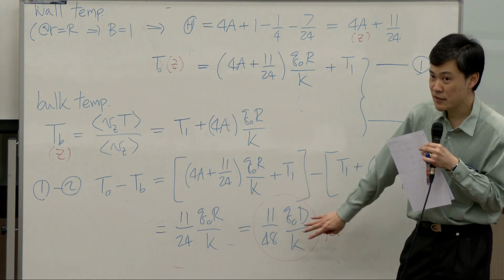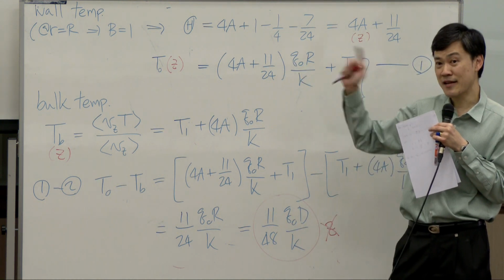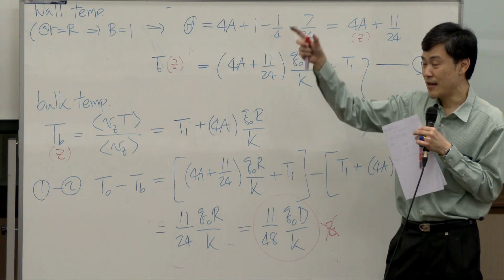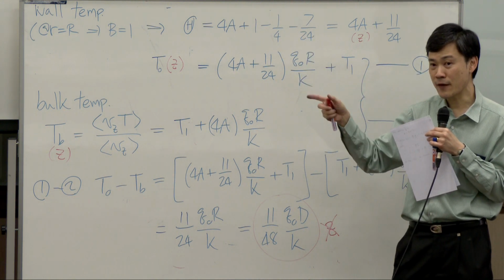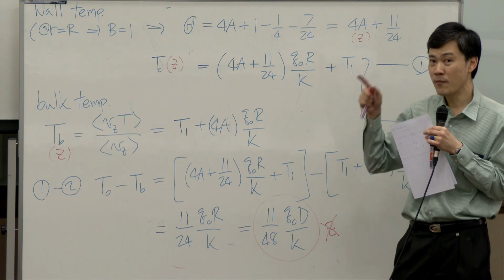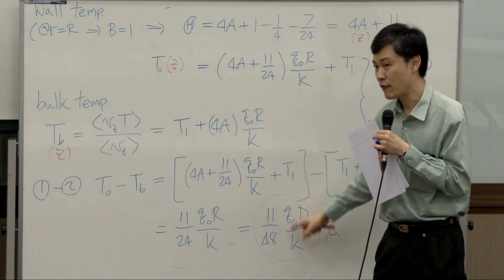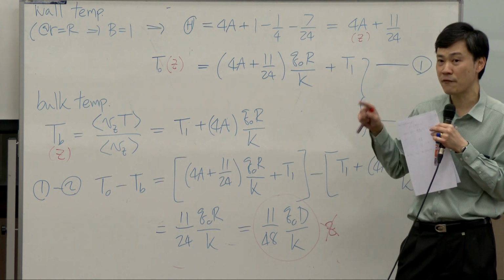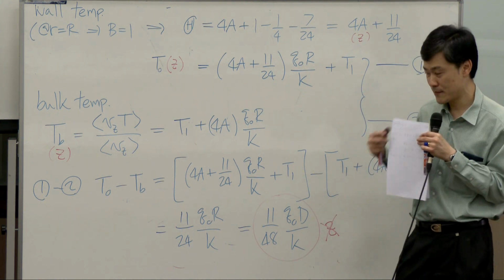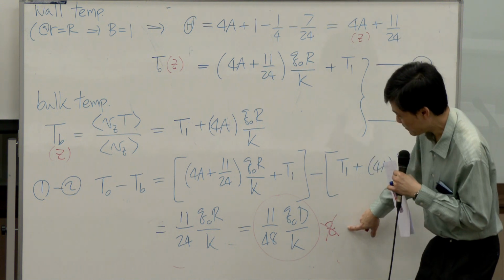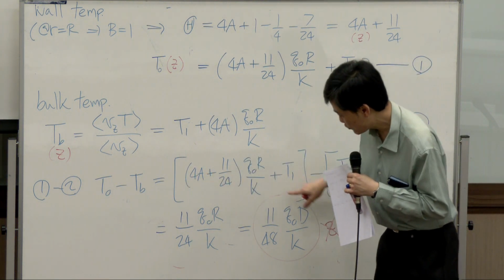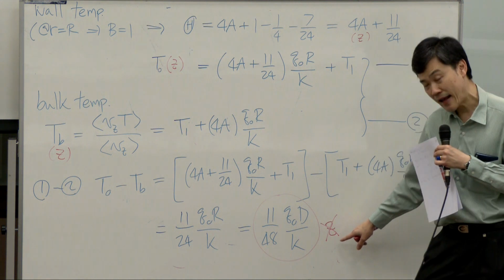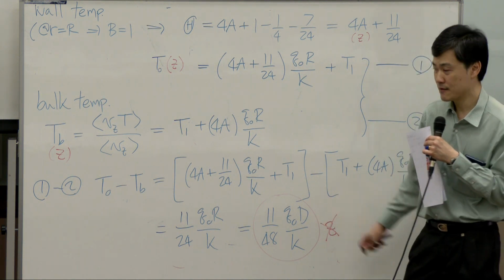That is consistent with what I said earlier: in our system, heat flux is constant. To make heat flux constant, the driving force is supposed to be constant. And the word constant means it's not a function of position. Okay? So at this point, once we get the driving force to be independent of the length, it means we got it right. Okay?